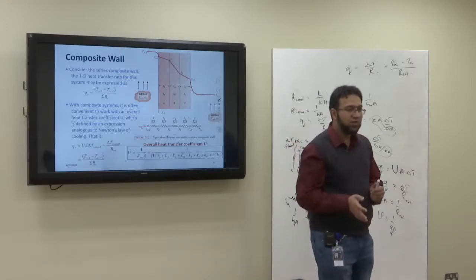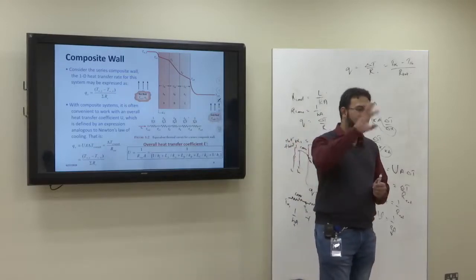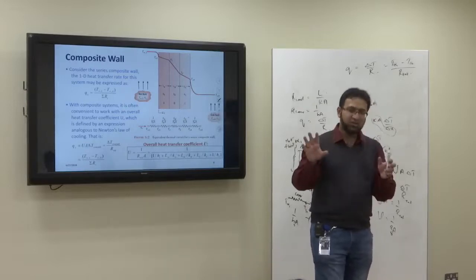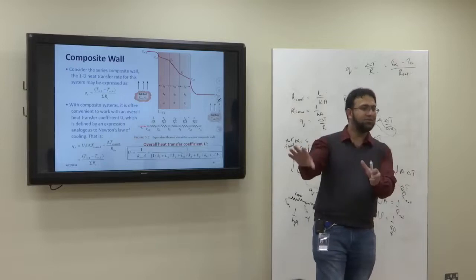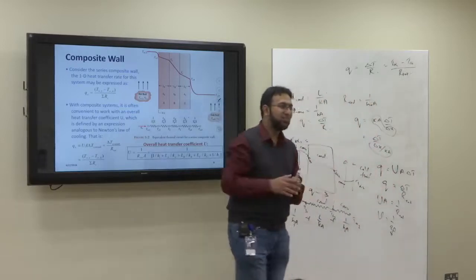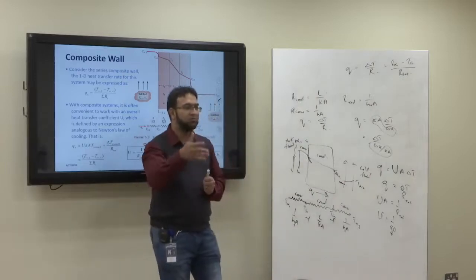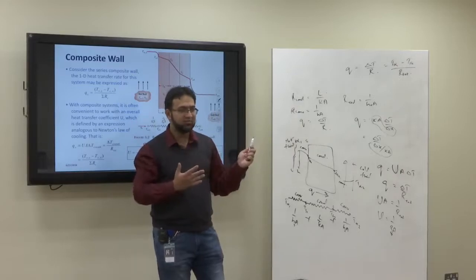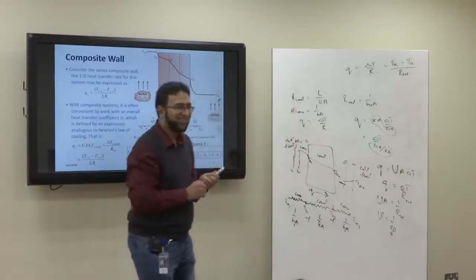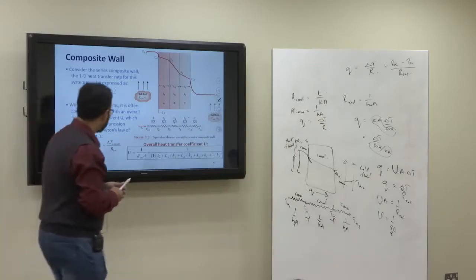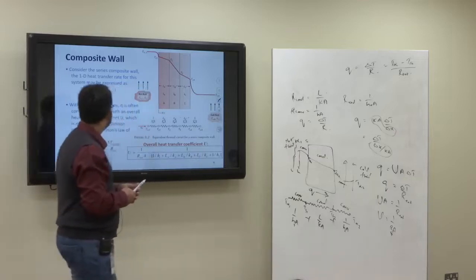Because when you give the U value, now you don't consider whether it is because of convection, conduction, whatever. Then they say, okay, we are the manufacturer of the material, we have determined it. This is the U value. They make things simple for the ones who have to use them. The user doesn't know the theory behind. Okay, so that's why knowing U is important for you. Is it clear so far?